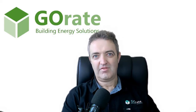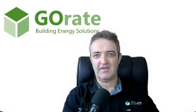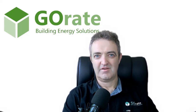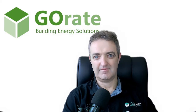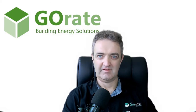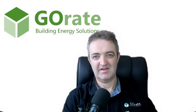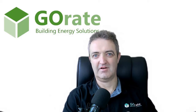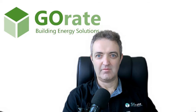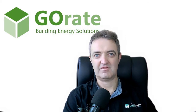So all of that air that goes out of the house is replaced by air from outside the house. So the air from outside the house is cold and that comes in. So you have to heat that. Then that air warms up and then it leaks out. Then cold air comes in, you have to pay to heat it again. So what you end up doing is just continuously paying to heat outside air. And that's just money floating out of the house. Anyway, with that, we'll go back to site, follow through the house, and we'll check out where those leakage points are.